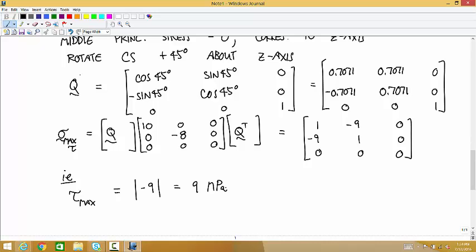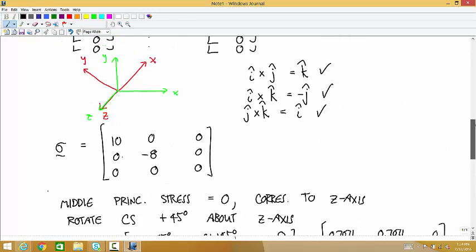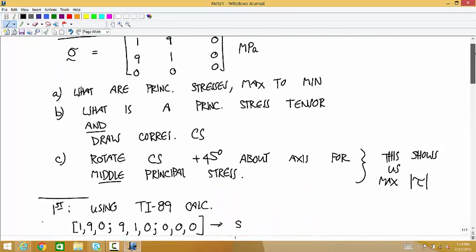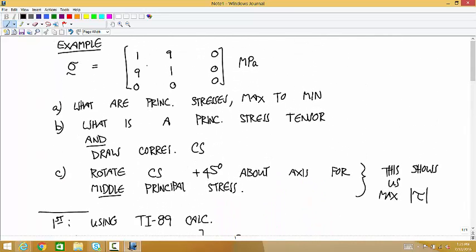Or another way of saying that is the stress tensor that I gave originally happened to be one where you saw the maximum value of the shear stress. And so there are some different strategies for determining whether a material is going to fracture. You would plug this value into that criterion, and it would tell you yes or no: in this loading setup that you have, this material is at risk of failure. Okay.